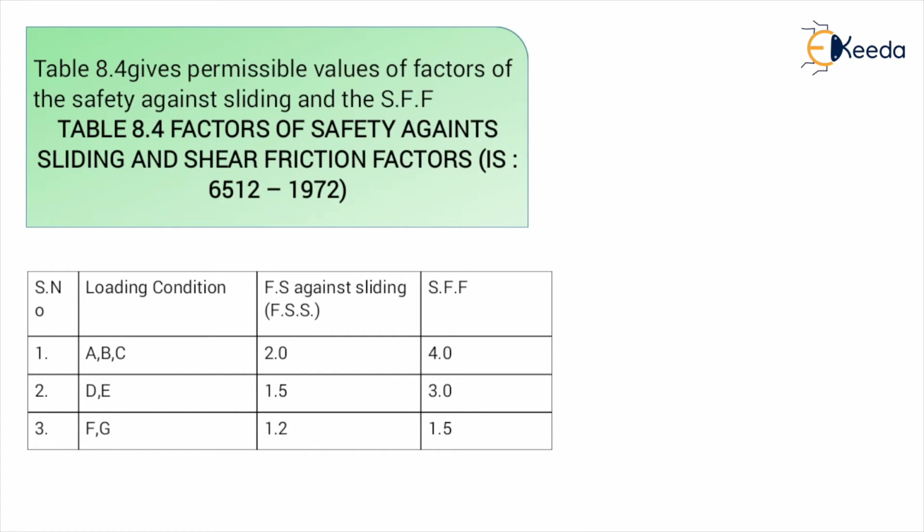In that, the flood water elevation, silt pressure, and extreme uplift, where there is no drain in operation to pass away this uplift pressure and the seepage water, is considered as an extreme load condition. And the reservoir empty condition means there is no water on the upstream side, so only the self weight of a dam will be considered and calculated.